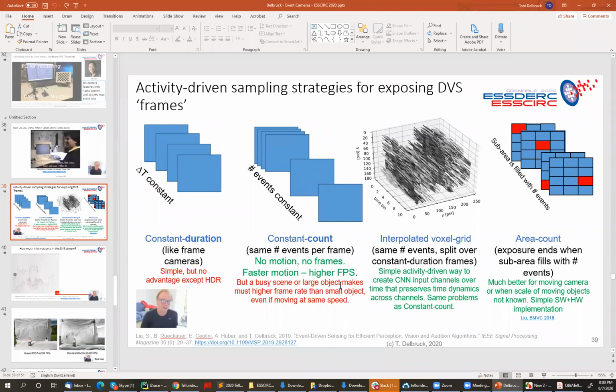The other thing is that I am using your video to illustrate the problem of latency, which is the problem with the constant count, I assume. You mean that it takes a while to collect those events? Yeah, that's true. If you care about really quick latency, you have to make sure that you terminate the frame quicker, right? And that's why all the cameras include this early packet timer. In the logic of the camera, when it collects a buffer of events, it makes sure that the packet is sent to the computer at most a millisecond later. It can get sent many times per millisecond, but every millisecond it sends whatever data it has. So that makes sure that the biggest latency coming from the camera to the computer is a millisecond. So you have to do stuff like that.